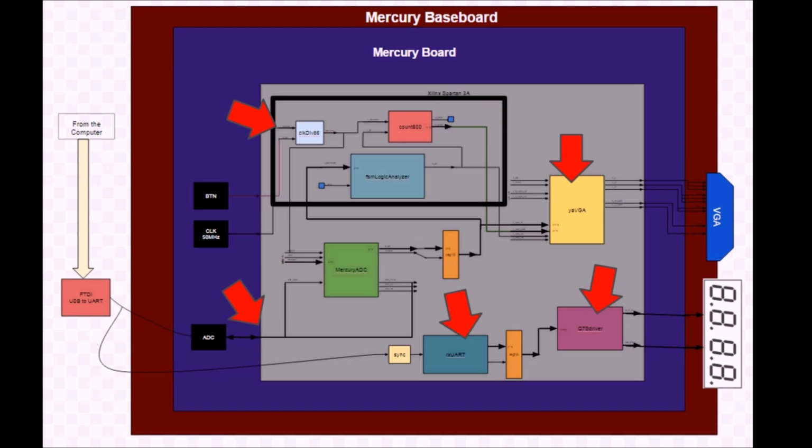Let's compare that to a microcontroller. The microcontroller very likely has its own dedicated hardware for SPI and UART, so no problems there. But once you get to the VGA, I've personally never seen a microcontroller having hardware to drive a VGA protocol. So you'll have to bit bang this protocol.